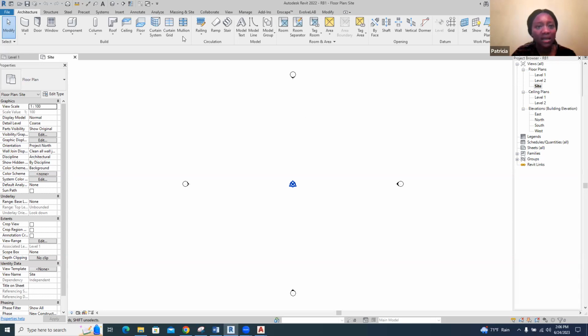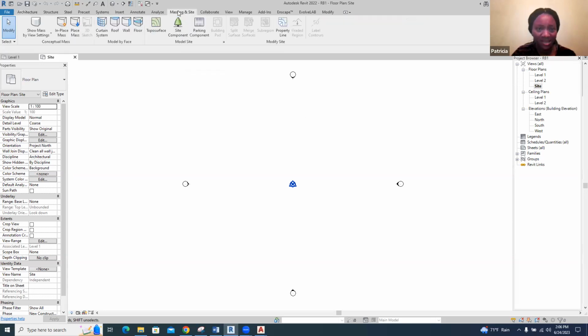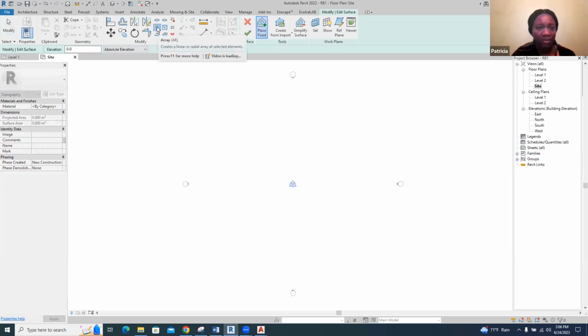To make our site, you go to this tab where we have massing and site. What we use to make the site is called the topo surface. So click on the topo surface. Like we said, it always changes depending on what you click. Once I click on that topo surface, it knows that I want to make a site. It will ask me what is the elevation of the site. Right now it's 0, which means it's flat land. If I leave it at 0 and click, it says place point. I click here.